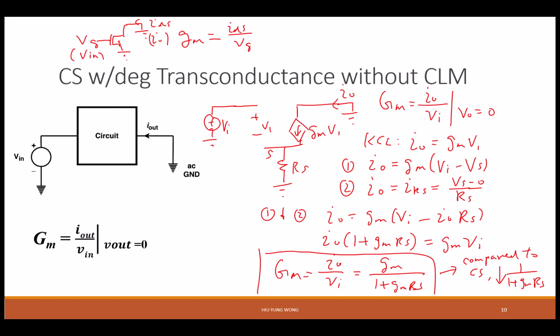Okay, so in this slide, we learned two important things. One is the meaning of the transconductance of a circuit. This is the definition, so put it in your cheat sheet. And how do you do it? You ground the output and again solve KCL and KVL to relate I out to V in. I out divided by V in. Is this okay?